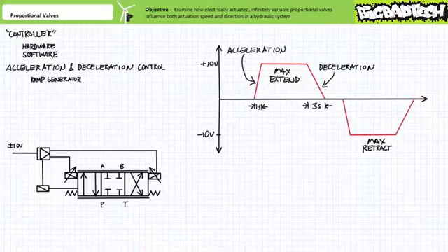A ramp generator is quite simply a steadily increasing or decreasing applied voltage over a specific length of time. The shorter the length of time to reach full voltage, the more sudden and abrupt the acceleration. The longer, the more gradual and smooth. Simple proportional valve controllers may use a single slope adjustment point that controls all transitions in all directions, whereas advanced controllers may allow for independently adjustable slopes of the acceleration and deceleration ramps for both straight-through and cross-connect positions.